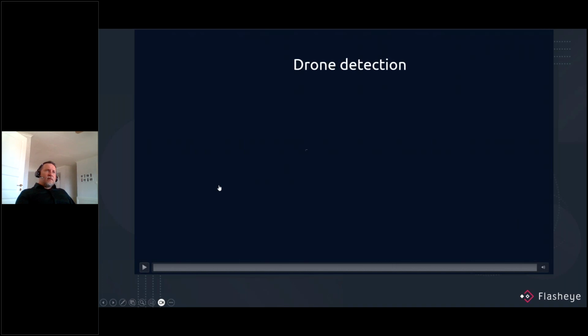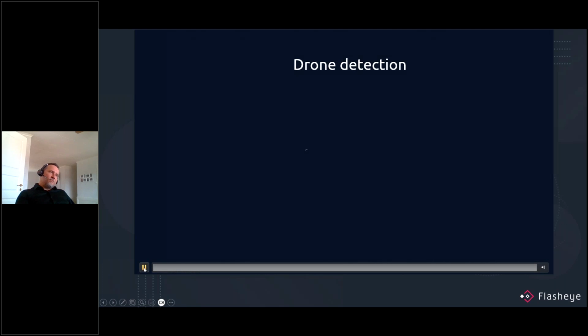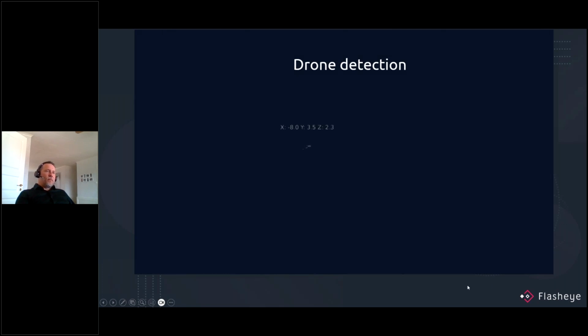We can also detect drones, and by using LiDAR for that, we set up sensors, we take the coordinate of the drone, and we point a good PTZ camera to it. So we use laser for detection and camera for verification. Then you will have 100% view for the operator. So this is how it will look in the LiDAR. We only see the drone, but we will keep track of it with a high-speed PTZ or several PTZs.